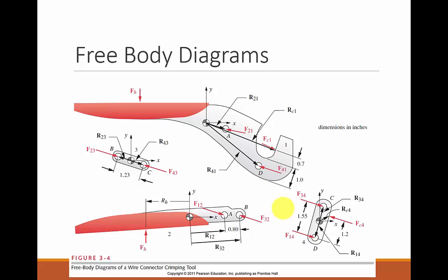So we need 17 equations. We have 20, and we have 3. That means we have 3 redundant equations. Okay, so we'll have to get rid of those three redundant equations. And now we're set up. This becomes just a geometry problem, a basic statics problem.